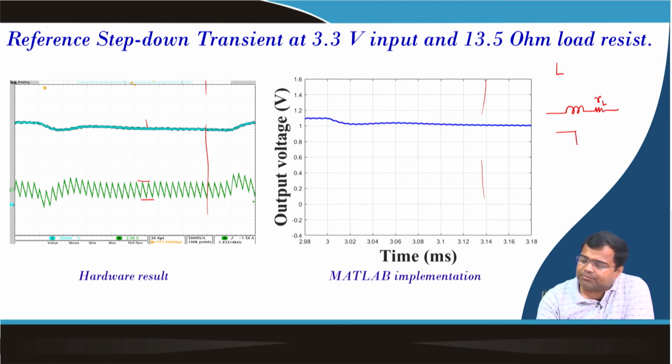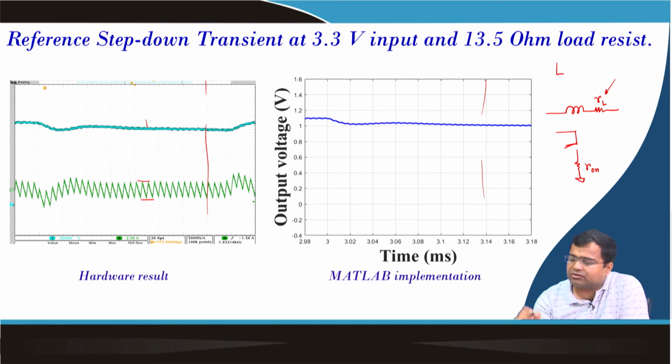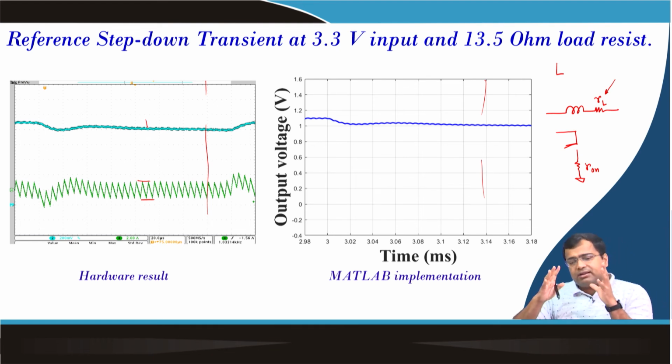Then switch we have considered the MOSFET, right. That means, if we take a MOSFET, we have to consider the R on. So, RDS on still some information will be available in the data sheet, which was okay, but getting this RL was very difficult, and we had to run multiple case studies to come to a conclusion what will be a realistic value of RL, but one can try out identification method.